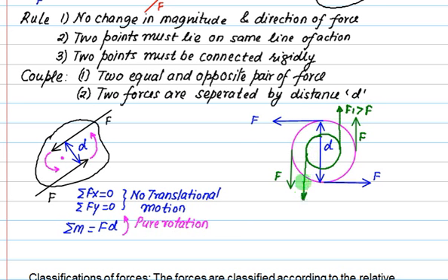Is it correct? Now this is the principle used in steering. If we have a smaller vehicle, then we normally use a smaller steering wheel, because we require less torque. But if you see trucks and luxury buses, their steering wheel is large. So to reduce the effort of the driver, we have a choice. We can increase the value of d by decreasing the value of F. Naturally, if the value of d increases, the value of F will decrease, and therefore the effort by the driver will decrease.